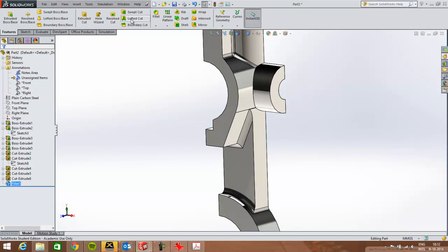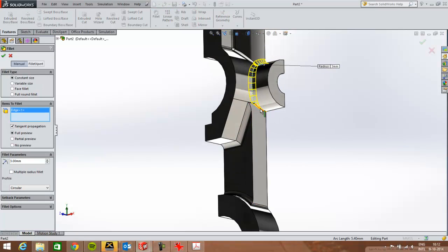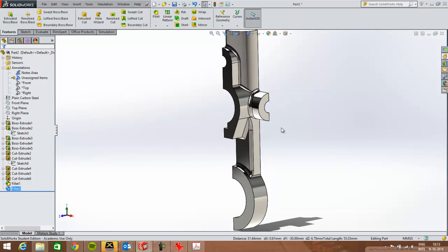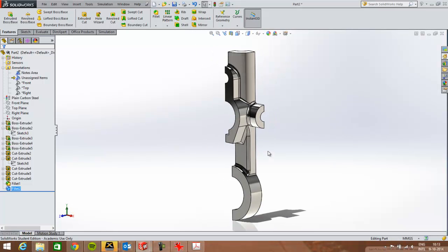So the way that you select the lines makes a difference for the part. If you select one line first and another line later, it makes a difference for the order of the fillets. And that's why it's so convenient to do it only on a quarter of the model, and then you'll be finished quite fast. So I think just experimenting with the order would give another result over here. I think I've got all the fillets, and now I can just mirror it again.